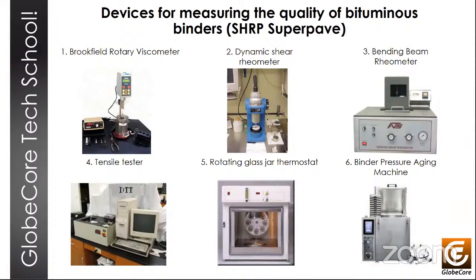So the features of quality assessment in accordance with European standards are simplicity, relatively lower costs, also repeatability and objectivity of the indications. The main limitations are the use of penetration and softening temperature, which indirectly characterize the performance of the binder in asphalt concrete, and also the limited ability to predict the service life of road surfaces using them. The European standard does not provide for the determination of the amount of evaporated diluent, nor does it provide for a softening point of the residue after heating.